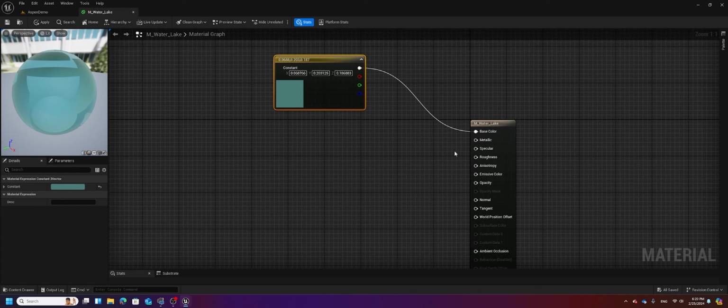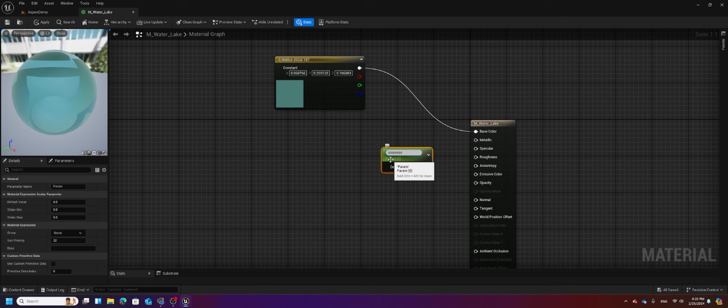Okay, the next thing we're going to do is I'm going to hold down the S key and left mouse click, okay? And that's going to give me a parameter, and this one's going to be metallic. I'm just going to go in order over here. I'm going to give this a 0.5 value. You can either Control D and duplicate it, but you need to make sure you change the name of it before you do anything else, because if you change the value in it, it's also going to change the other, because it's the same name, so it'll keep all the constants the same.